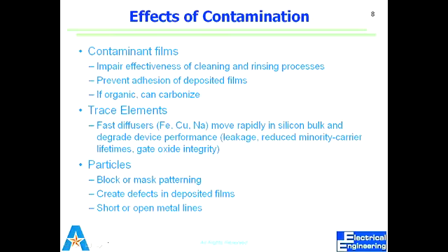Elements can diffuse in the silicon and degrade device properties. Again, transistor, remember always transistor, we need to have control over the gate. If I can't switch it on and off, it means I'm losing control over the gate. So if I flip it and nothing happens, I don't need it. It's not giving me any control. Same in a transistor, if I cannot switch the gate on and off to make the device conduct, I am losing gating effect. That can happen with trace elements.